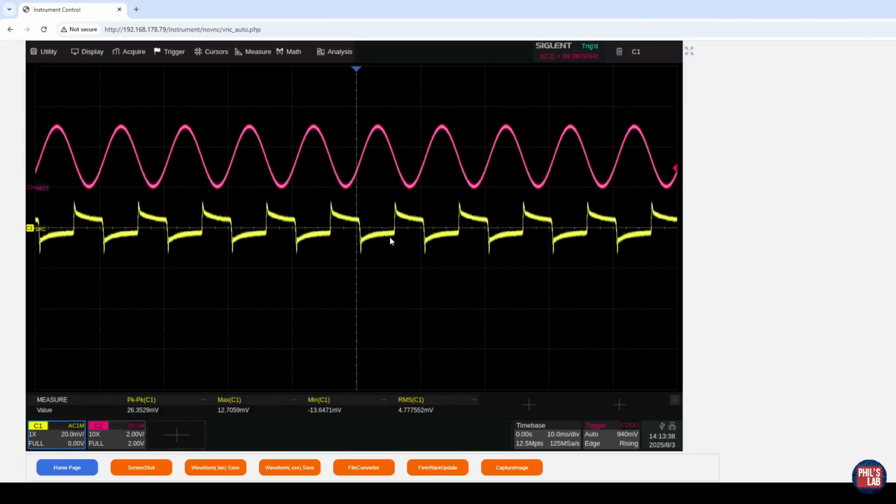At DC, our series resistance is whatever the DC resistance is we measure of our power distribution network. So typically smaller than the AC impedance. So that's why we return back to the nominal 1.8 volts. So this is quite cool to see that the current demand, because of the non-idealities of our power distribution network, projects noise or induces noise onto our voltage rail as we can see here.